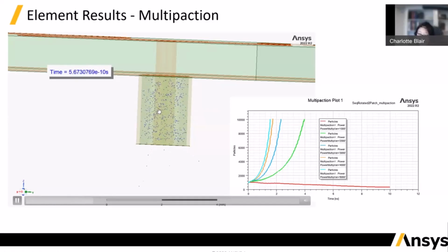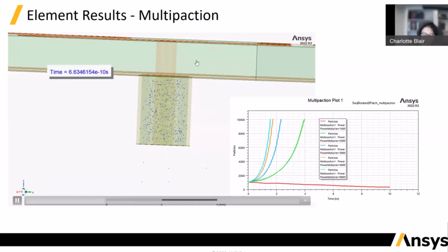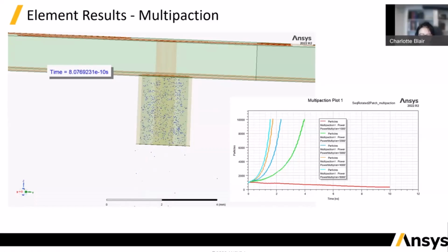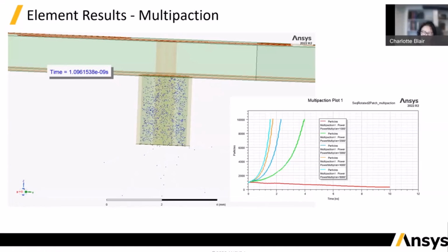The electrons, yes, can be in the dielectric, but we need a vacuum because it's space. So I created an air-filled coax, and this is where the electrons are. They're moving in all directions. It's not just X, Y, and Z. They may be accelerated through the field here. Perhaps they're emanating from that inner pin, hit the sidewall of the connector and bounce back. And perhaps just at the time of resonance of the RF signal and the electron velocity, it may produce another electron, maybe 2, 3, or 4.